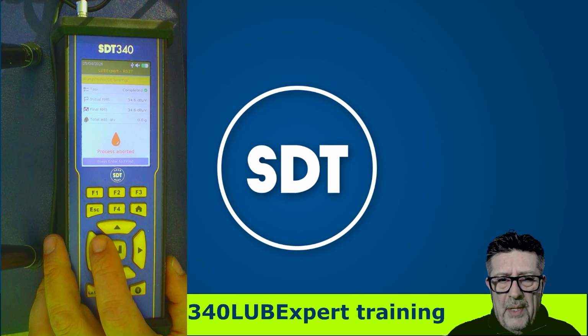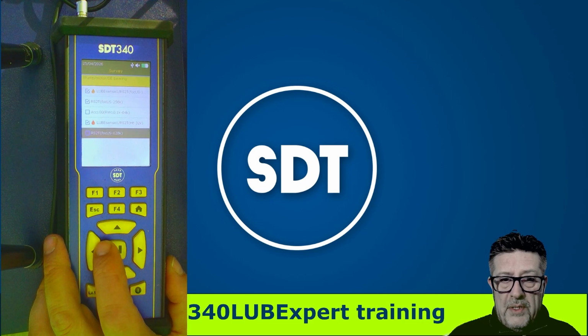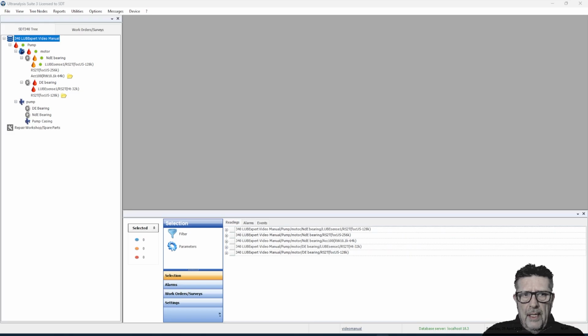Process status of the bearing is process aborted. I didn't add any grease. Just notice something is wrong, and I just exit the process. Now let's upload this to the software and see how it looks like when we upload the data back. And we are now back. We downloaded the data from SDT340 to US3. Now let's take a look at the data a little bit.